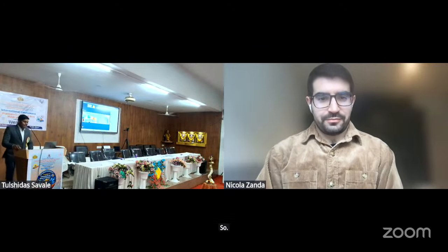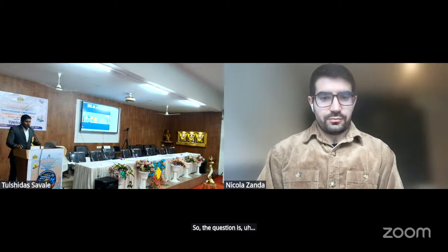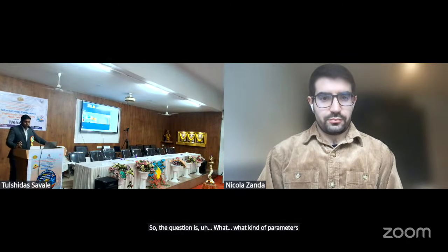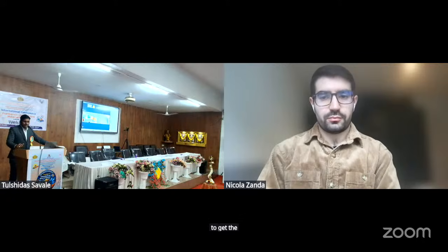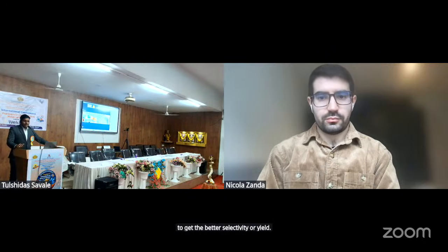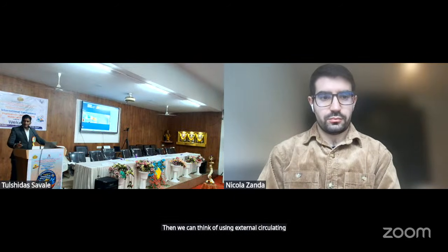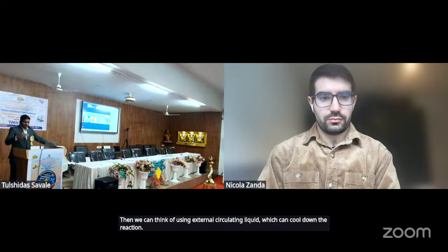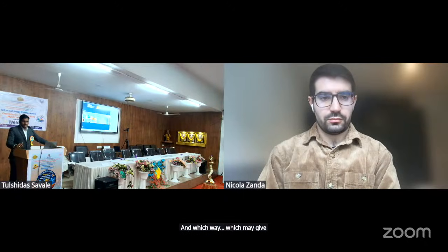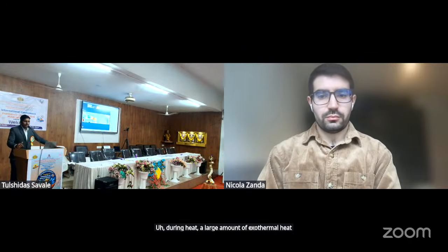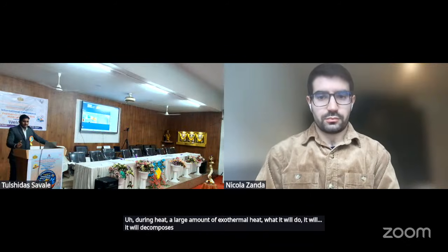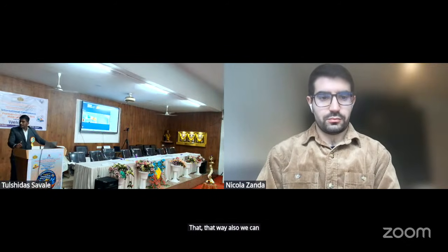So the question is what kind of parameters we can tune to get better selectivity or yield. For that reason, if the reaction needs cooling, then we can think of using an external circulating liquid which can cool down the reaction and may give a better yield, because a large amount of exotherm or heat will decompose our product. That way also we can lose some of the yield.